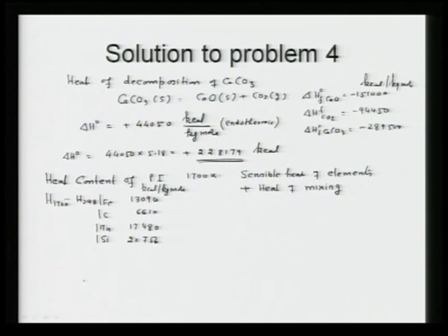Heat of mixing: because we have carbon in solid going to carbon in liquid, 1 weight percent, the heat of mixing is 5.4 into 10 to the power 3, plus, kilocalorie per kg mole. Similarly, silicon solid to silicon liquid at 1 weight percent, mind you it is minus 28 into 10 to the power 3 kilocalorie per kg mole.